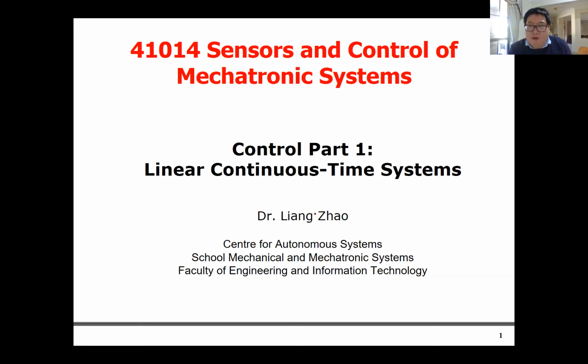Right? For example, if you want to do a 3D triangulation from a stereo camera, then you have to do the feature extraction from each of the images and then do the feature matching, right? And also, when you do this kind of matching or checking, there are a lot of outliers in it, which means wrong matches. So how do we remove those outliers? Then we introduce a very, very famous method called RANSAC.